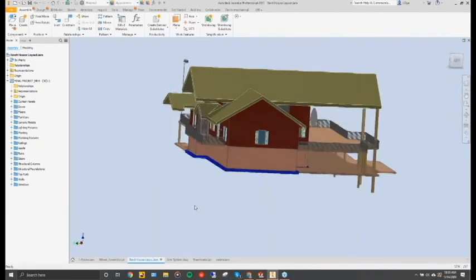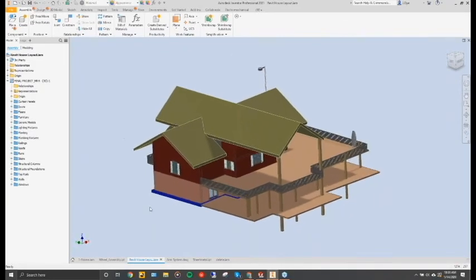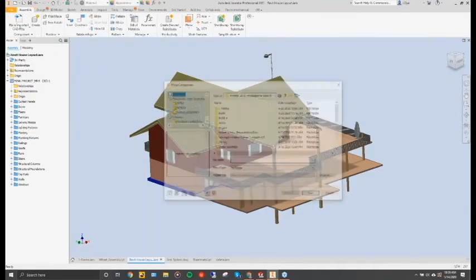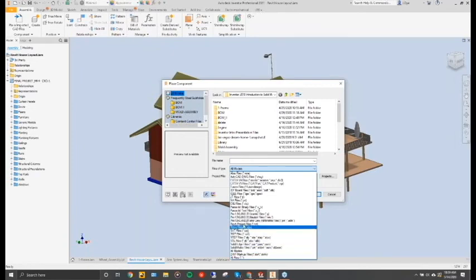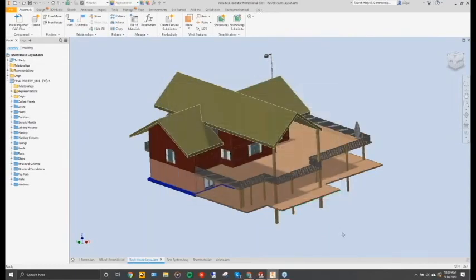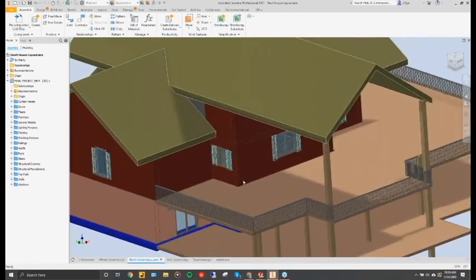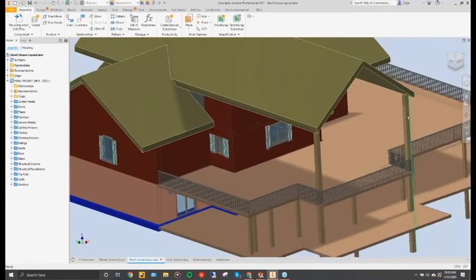All right, this particular improvement I'm not going to actually demonstrate because I don't have Revit on my machine, but this is in fact a Revit file that I brought in using the AnyCAD technology. So just click on Place and select Place Imported CAD File. From here, you just need to specify which non-native Inventor file you want to bring in. Whatever the file extension of the Revit file is, you select that through the filter here, bring in that file, and I can use my Inventor tools and maybe model another beam or whatever it may be